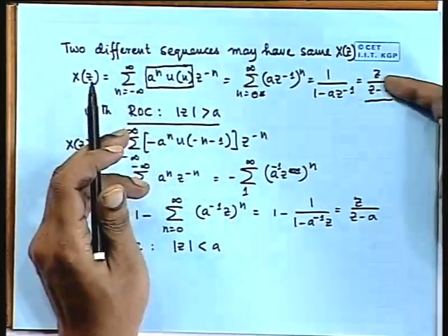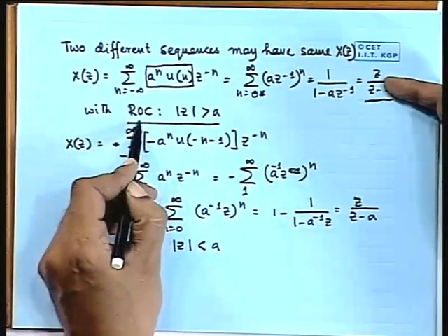This is very important. This function has this z transform over this region of convergence. That is a complete statement. Saying this function has this z transform is not a complete statement to make. The function cannot be uniquely obtained unless you also specify the region of convergence, which we do not usually do.